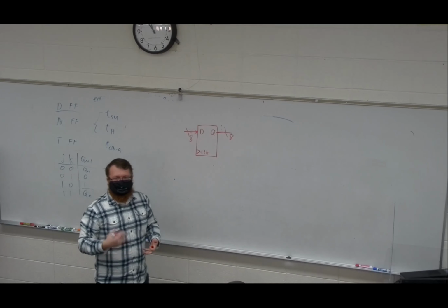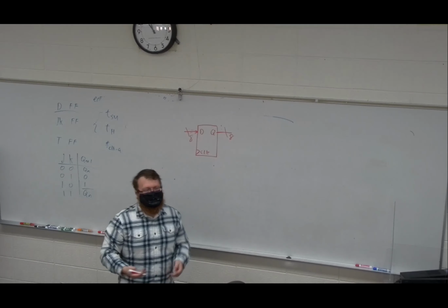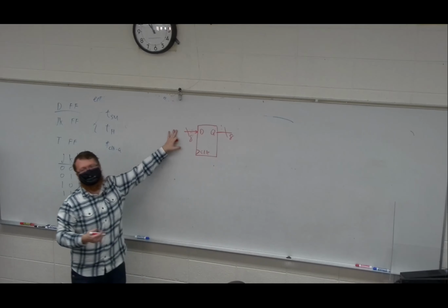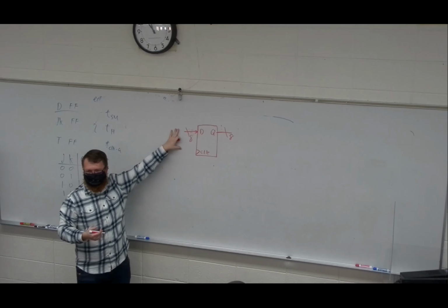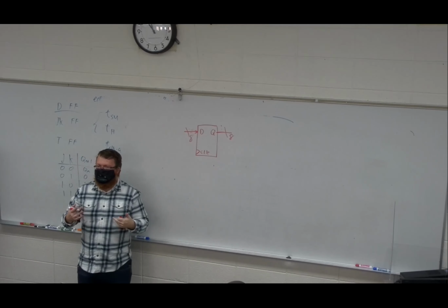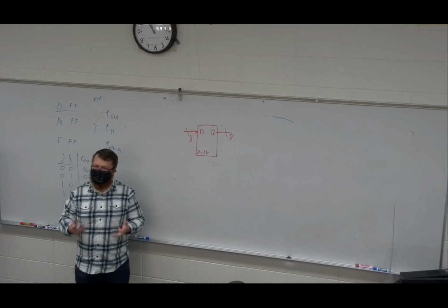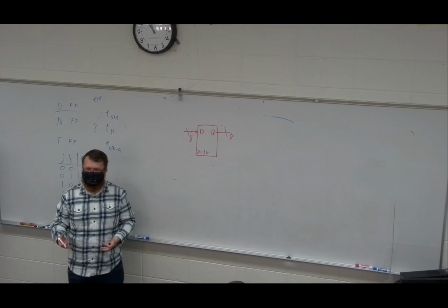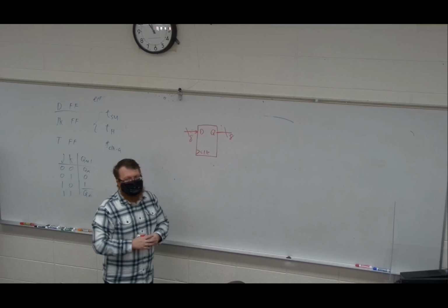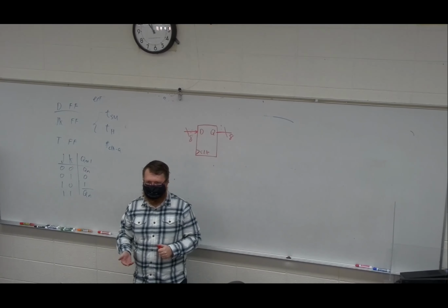But what happens if I want to use more and more and more memory, right? This starts outputting tons and tons of wired connections everywhere. We are realistically limited to a finite number of wires that we can have running around. The more wires we have, the more room it takes on one of our devices. So this is where a new concept comes in that we call addressable memory.